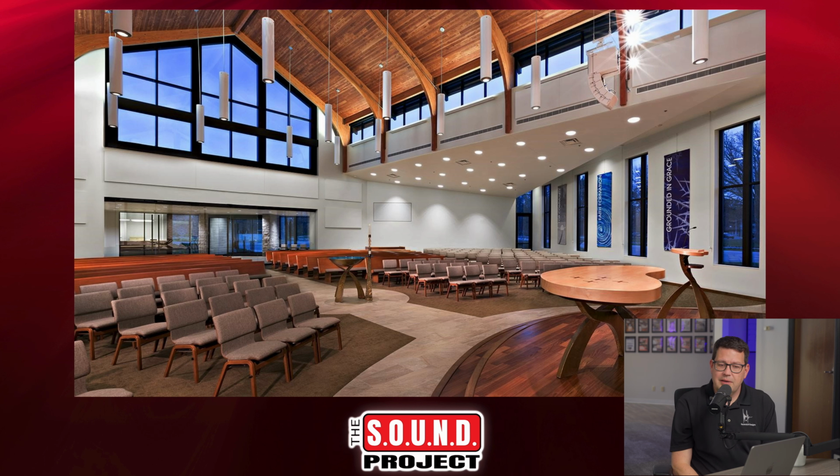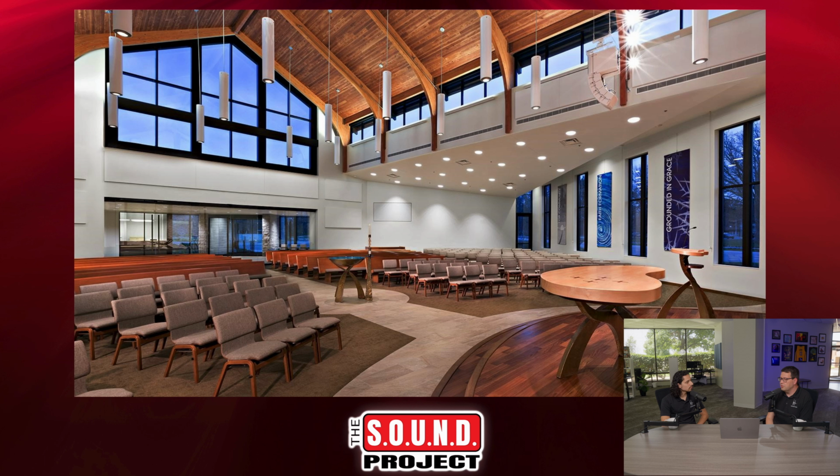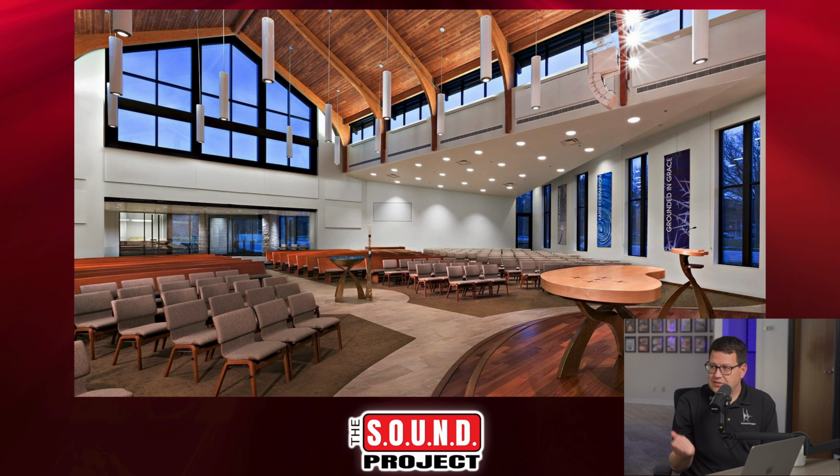What's nice about this space is that you can see some panels when you're looking for them, but when you walk into the room, it's not something where you just see blanketed acoustical panels everywhere. The main ones that you see are around those glass doors in the back there. There's some white panels to match the walls. And then there's some up there in the clerestory area by the speakers, right below the windows, to catch some of the early reflections that come off of those line arrays that are hung up there.